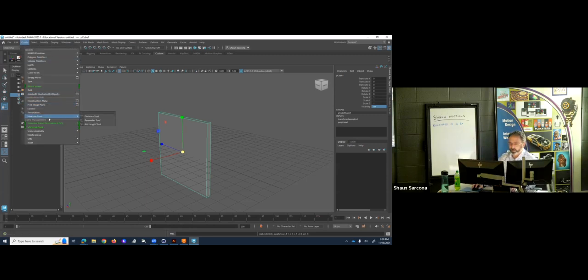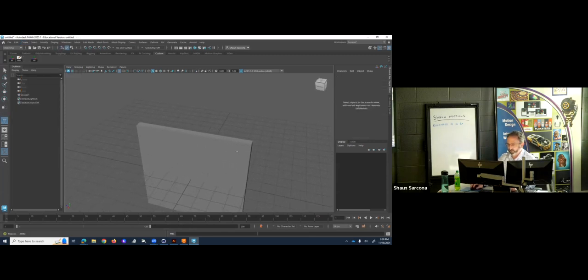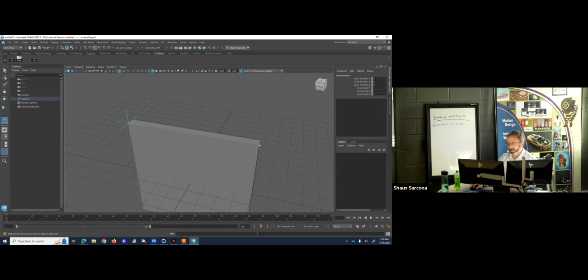So there actually is a measuring tool inside Maya where we can go to distance. And then we just hold the V key down and click on one corner. Still holding the V key, click on the other corner. And then we can see that definitely is 8 centimeters.